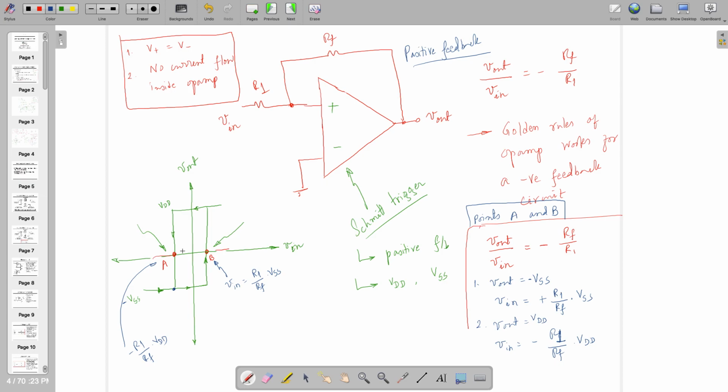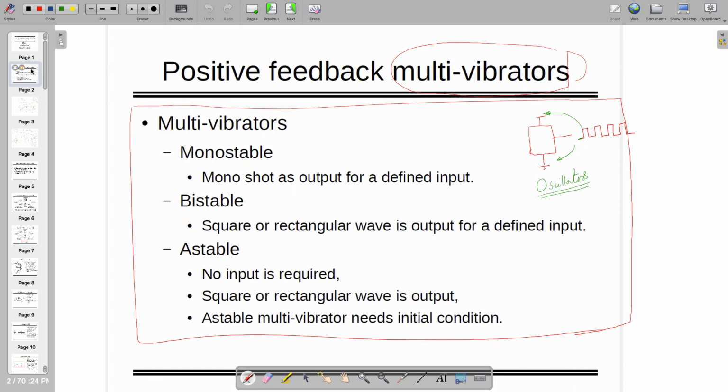If you want the circuit to be an amplifier, you need to keep the circuit in negative feedback, and you need to make sure that its phase margin is greater than 45 degree, right? This is the golden rule. Please follow that. Now if you understand that, and this was just a background of the work, we are interested in negative feedback, by the way.